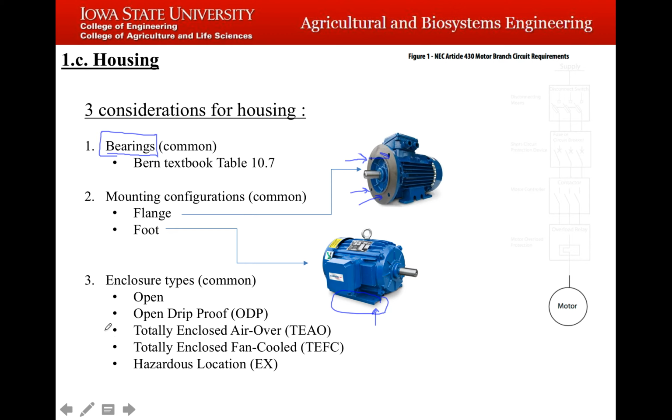Totally enclosed, air over. Okay, totally enclosed, fan cooled. And then maybe one of special note, hazardous location, explosion proof, intrinsically safe areas where we have explosive environments. We want to be very careful about the type of motor that we put in those environments. But there are all different types here.